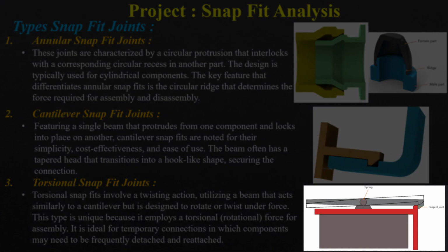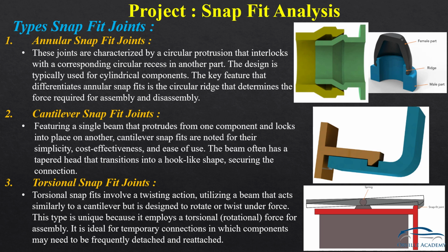You can note in the image, the red part is the location where the snap fit will get locked. In the image, there are two positions of snap fit shown. One is in the grey color which is at the engaged position and one is with the hollow white color which is at the disengaged position. Engagement or disengagement of the assembly happens by twisting the arm about the spring location. This particular arm is mostly preloaded using the spring.